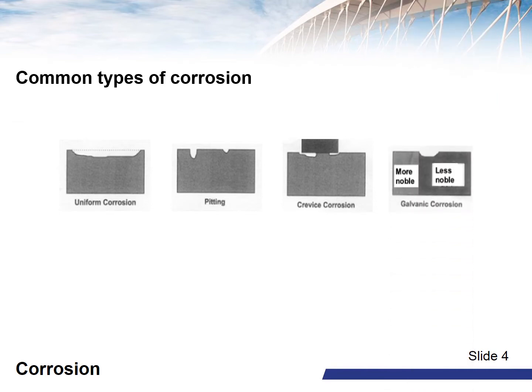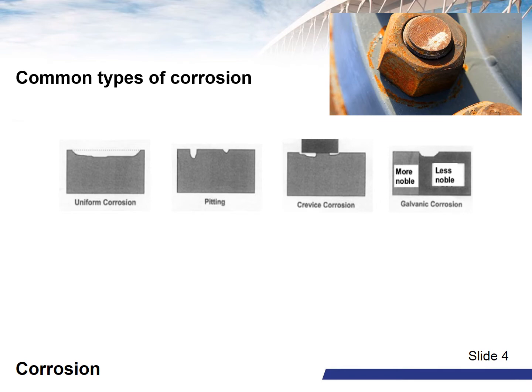Galvanic corrosion. This form of corrosion occurs when two different metals with physical or electrical contact are immersed in a common electrolyte, such as salt water, or when a metal is exposed to different concentrations of electrolyte. Where two metals are immersed together, known as a galvanic couple, the more active metal, the anode, corrodes faster than the more noble metal, the cathode. The galvanic series determines which metals corrode faster, which is useful when using a sacrificial anode to protect a structure from corrosion.